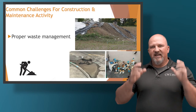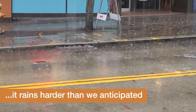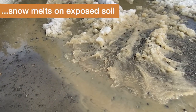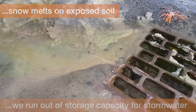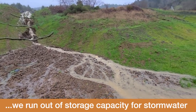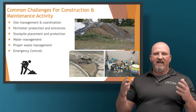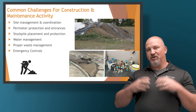And then we really need to have the what if. We need to build contingency into our program. What if we experience a very difficult rain event? What if we have snow that buries our project and then melts on top of it? What if our project goes longer than we anticipated? We need to build contingencies into our management program so that we can be successful even during difficult periods when we know that with any type of construction activity, the best laid plans that you start in a dry environment are going to change as you go out into the field.